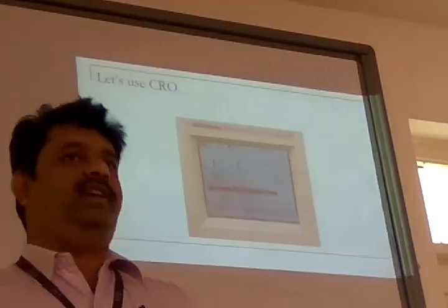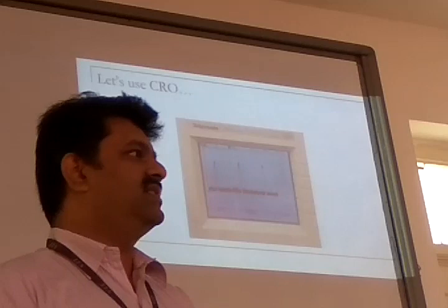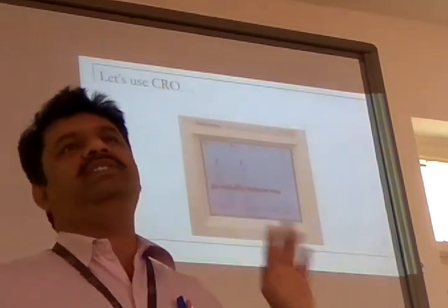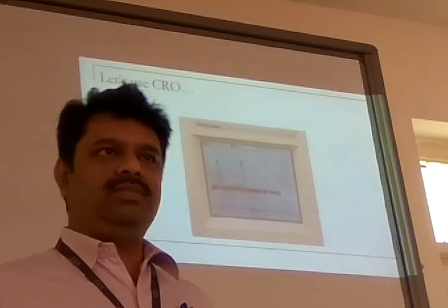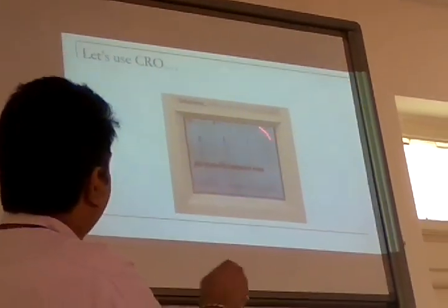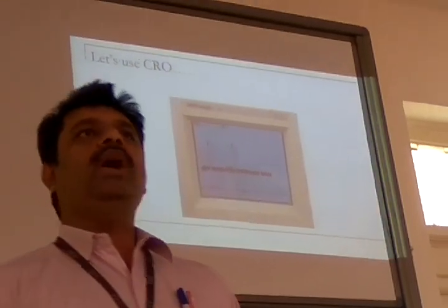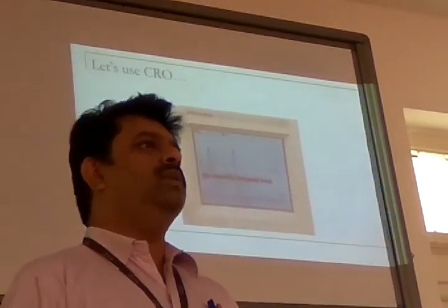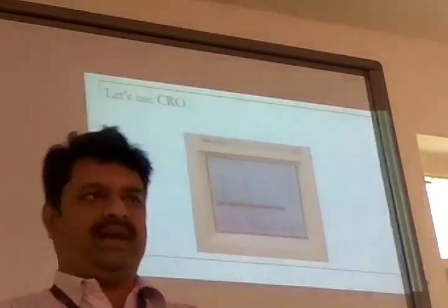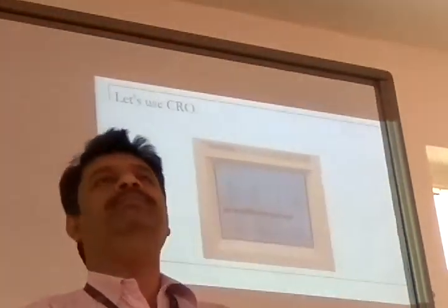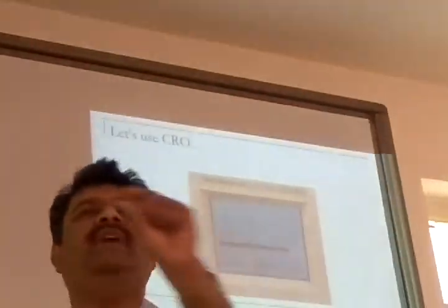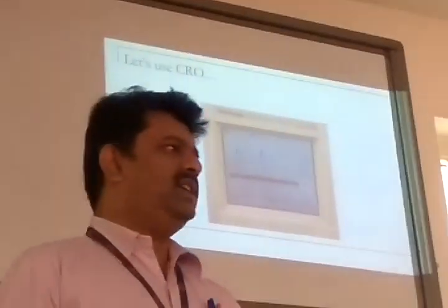So we cannot afford that kind of cable for all the sensors that we have. So we buy some normal wire, and the wire picks up noise, which then comes inside. So I get something here. When I get noisy signals, I may not be able to get the actual temperature. Because normally what multimeter kind of devices do is they take the RMS value of whatever voltage is coming here.